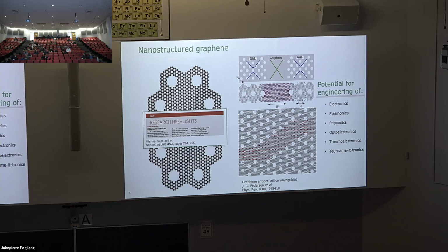Right. So you're trying to open a gap, right? Yeah. So just to take advantage of graphene having large mobility. Yeah. But why do you have to kill it, right? In principle, if you could do something that is atomically perfect, the mobility is preserved. But if the holes that you're going to make in the graphene are disordered and messy, you have process residues on the graphene, for sure you're going to kill mobility.